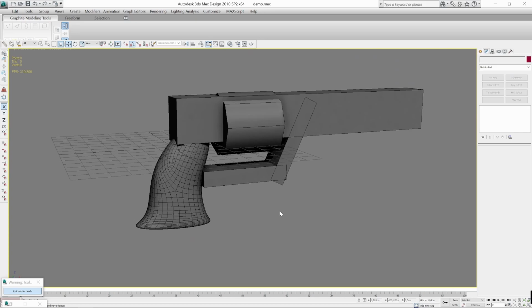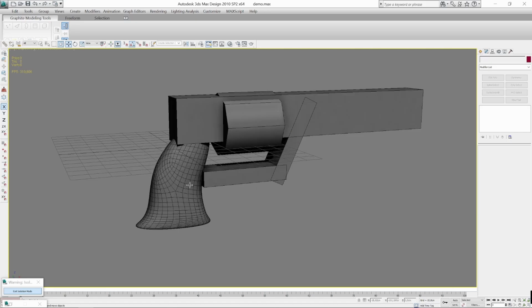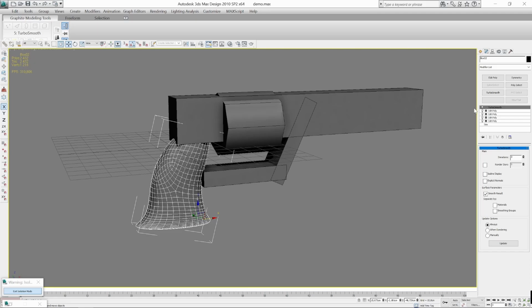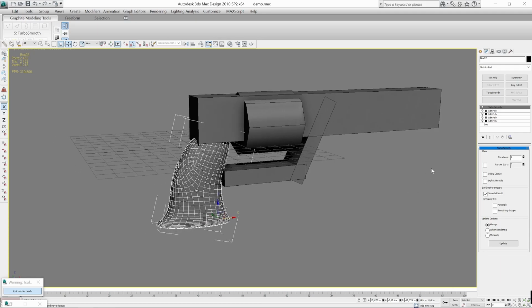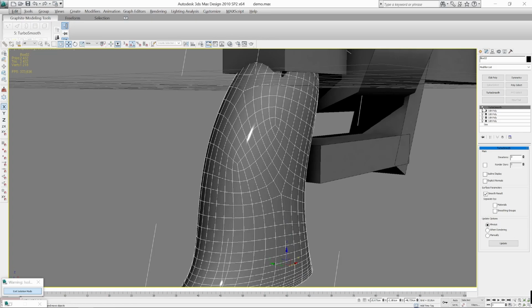And that's really the only two techniques: you add boxes, and then you add your turbo smooth or your smoothing operation, or what's that? I keep forgetting the name. Subdivision surface. So you add that, and then you see that okay, it looks horrible, and then you go and fix it. And yeah, well, here this might be a good example to show.